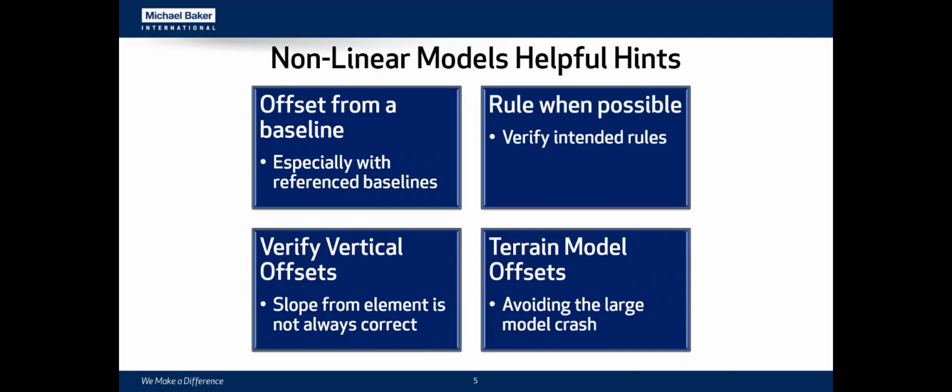I see a question about why would I manipulate the boundary? Isn't that considered a project limit? I'm not manipulating the boundary for the tie-down location at the ground from a slope stake line perspective. I'm manipulating the boundary when it's connecting two models together. So if I have a seam between an intersection and a main line, that boundary line that I'm creating, I want to make sure that that is 100% tied to the model that I'm connecting to.